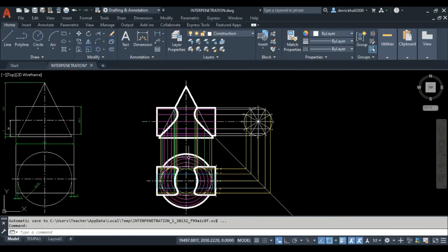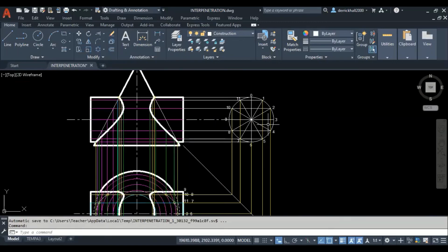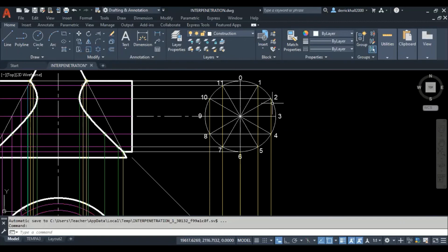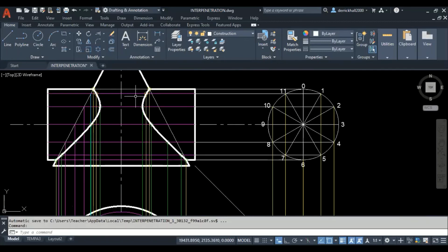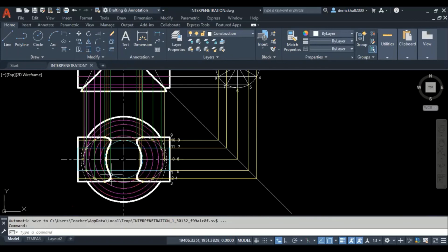Okay. So once again, the technique that we use here is to draw the given views. We create some sections through the elevation, and to be uniform, what I did was to draw a cross section of the cylindrical portion, the cylinder, and divide it into 12 equal parts. And I project each part across, so I get different sections: 1, 2, 3, 4, 5, 6 sections. And each of these sections is represented in the plan as well.